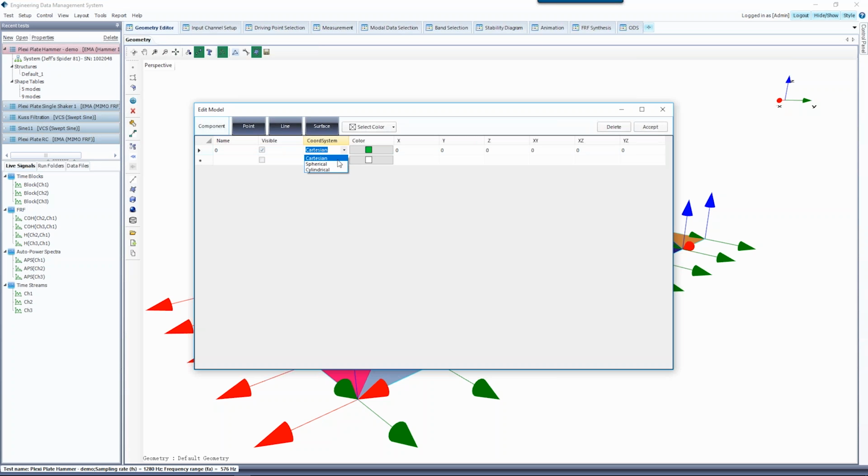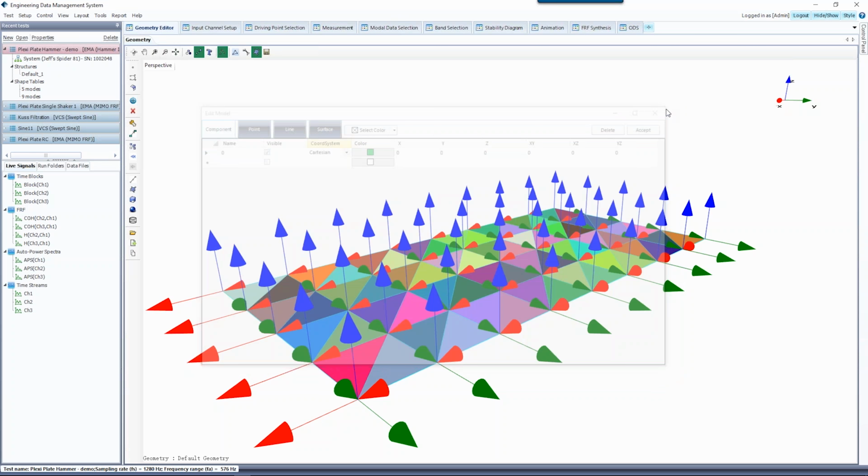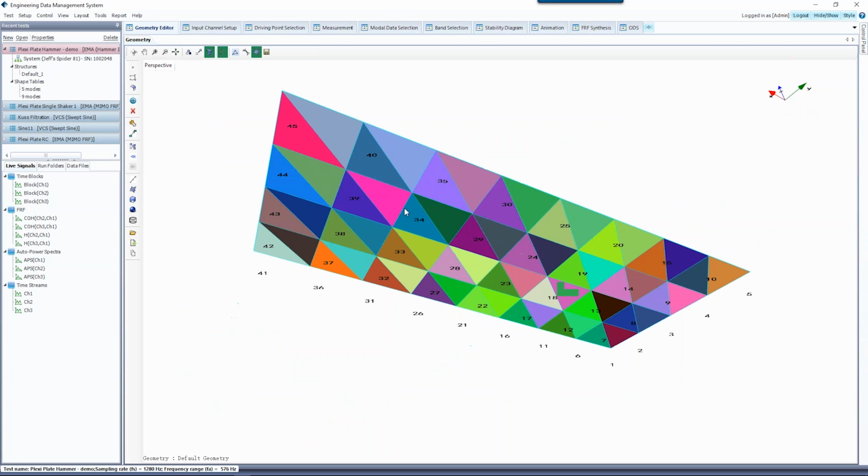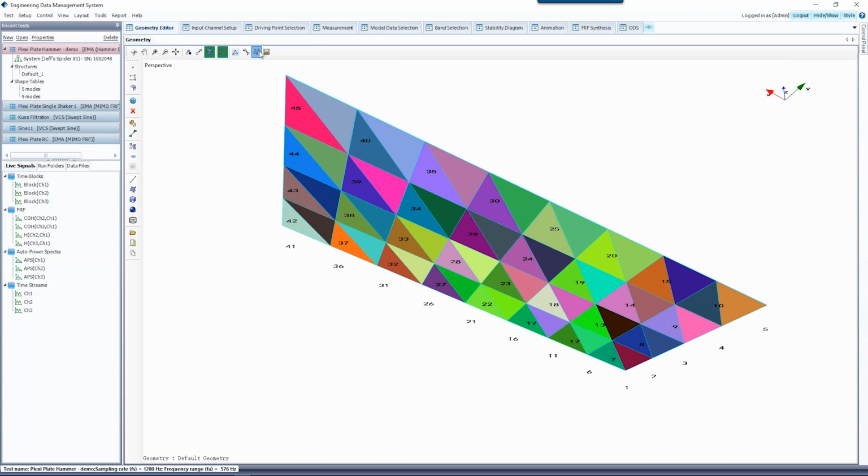And for the display, you can turn the points on or off, and you can turn on the direction for each point. For every point, you can change its local angle, which people call the Euler angle. So if it's tilted, you can define, say, a rotation around the z-axis of 10 degrees or 15 degrees, whatever, but you need to specify it.